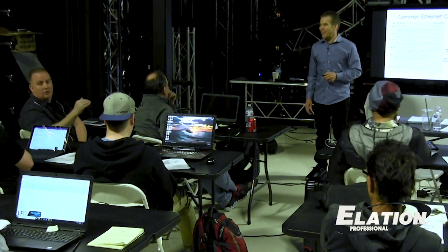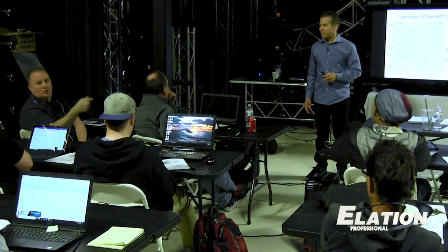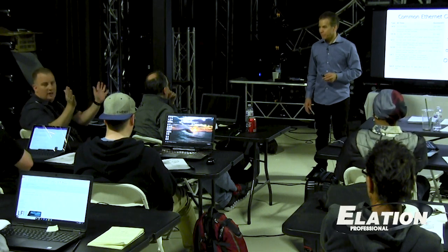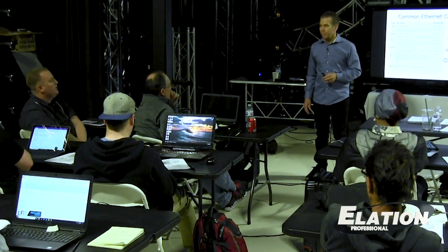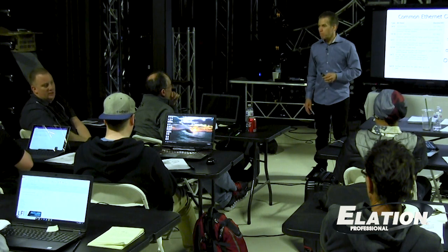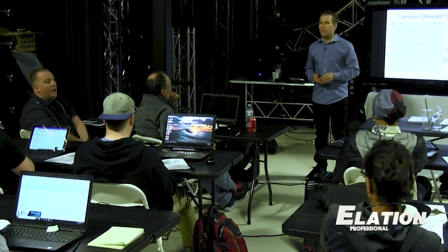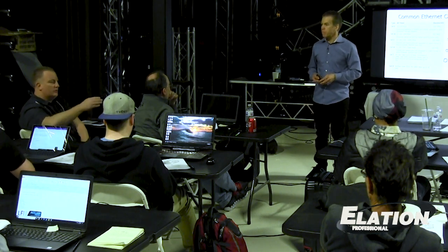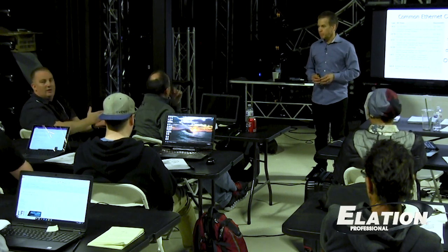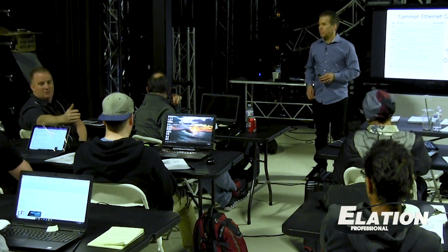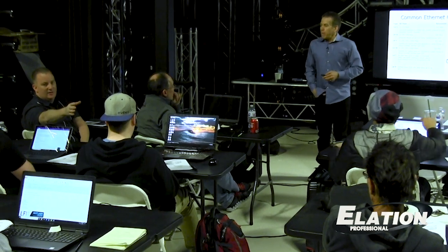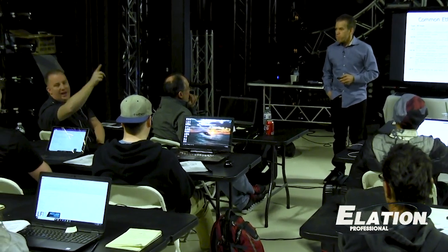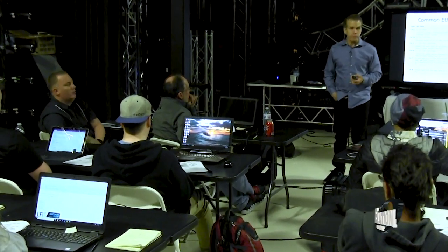You're testing good in the lab. You get it out to the show, and all of a sudden you get this bottleneck. Because you patched into the copper that's there, and they say, well, no, it's fiber. Well, no, it's fiber from where they did their rebuild to a patch panel or a media closet somewhere, and then all of that is old copper running through the system.